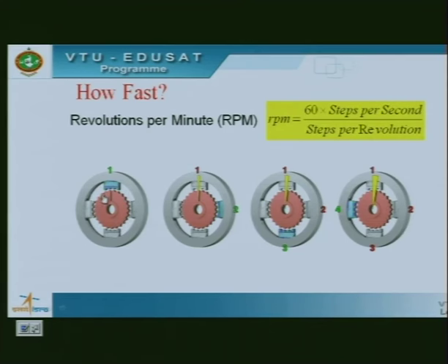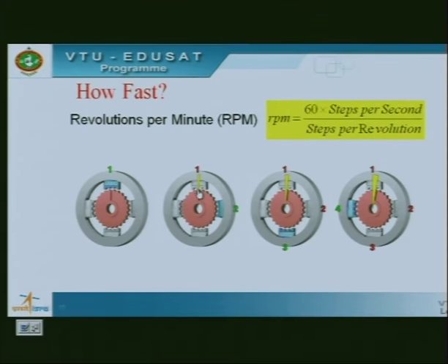You can see the central rotor having the teeth. So, there are multiple teeth. In the first step, when coil 1 was energized, it is pointing to coil 1, a particular tooth, and in the second step when coil 2 was energized, that tooth moves by a very small angle, and that angle can be 0.9 degrees or 1.8 degrees depending on how many teeth are present on this rotor shaft. So, if I have 25 teeth for example, then the movement here will be by 3.6 degrees.